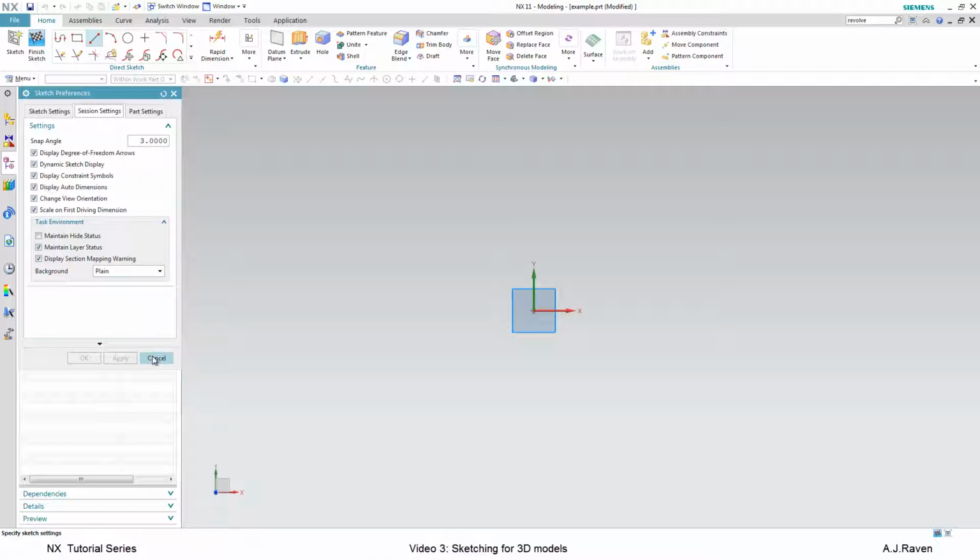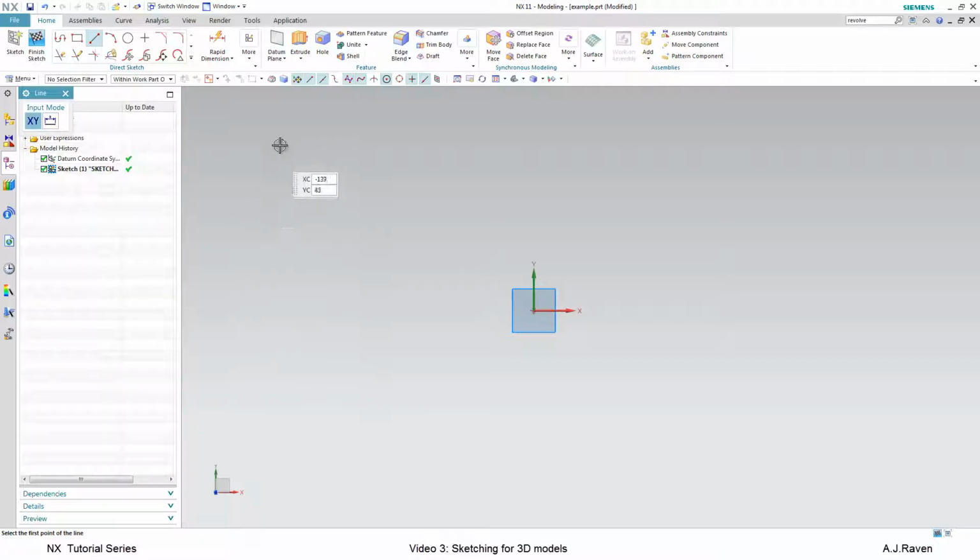Selection intent is an important part of modelling, and there are a range of tools to help ensure you are selecting and editing the features that you intend to. Selection tools are all located in the small ribbon above the model window. These can be turned on or off to help you sketch as intended. For example, I often find myself turning off the Point on a Curve snap tool, as most of the time my lines need to connect to more defining points, such as endpoints, midpoints, or intersections.